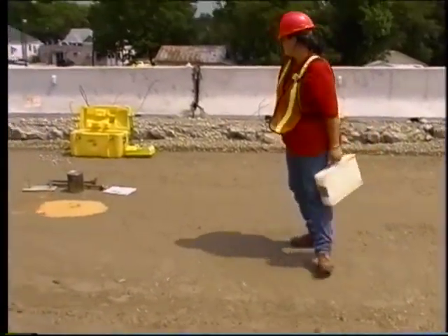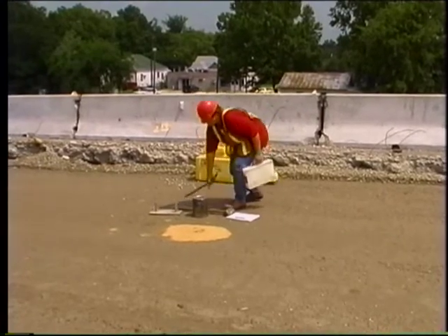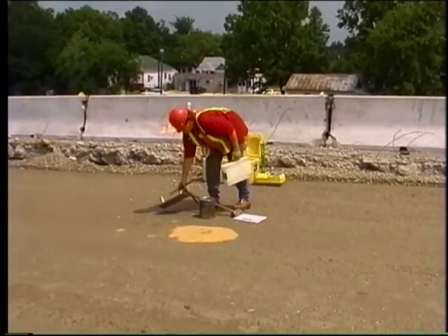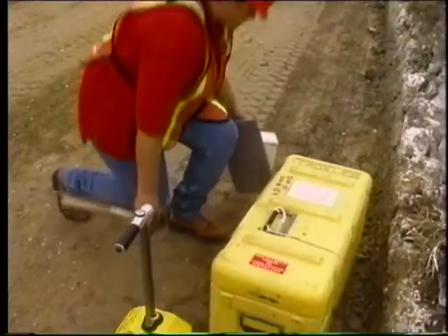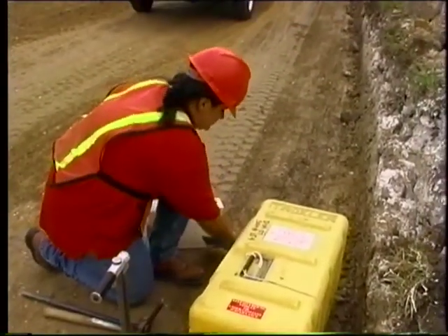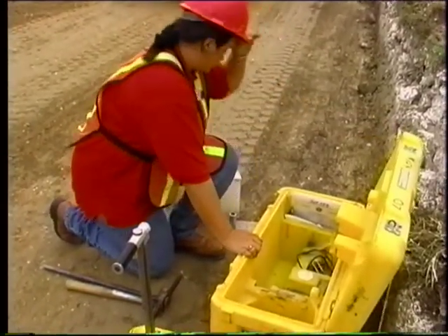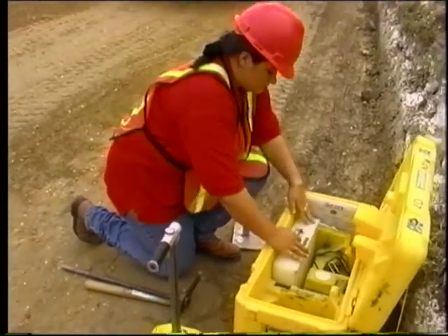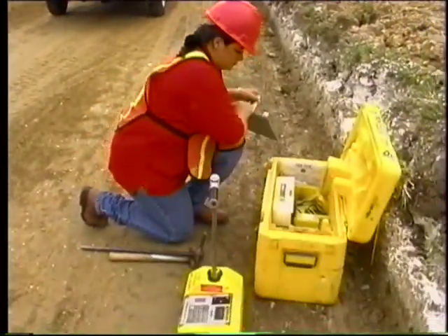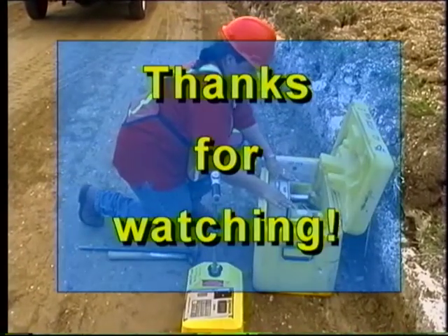Using the maximum dry density figures from the Proctor test or the moisture density curve, do calculations to obtain percent density for the material. If you encounter any problem, are in doubt about a situation that arises, or if the device is lost, stolen, or damaged, notify your supervisor immediately. Remember, if used correctly, the nuclear device is a safe and effective means of obtaining in-place density for an embankment and base course. Thanks for watching.